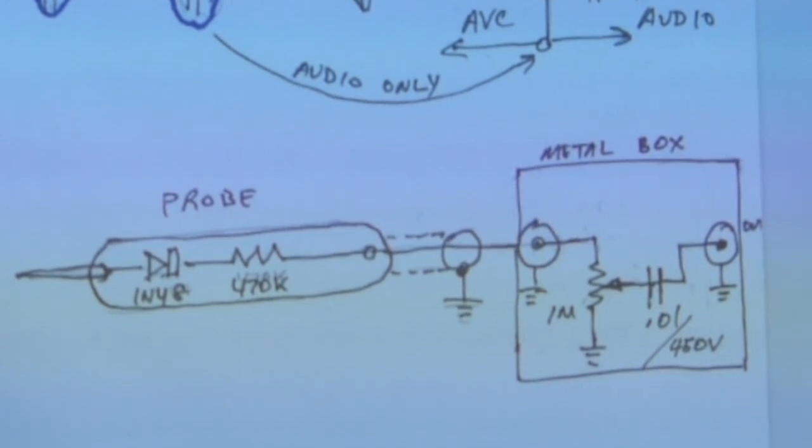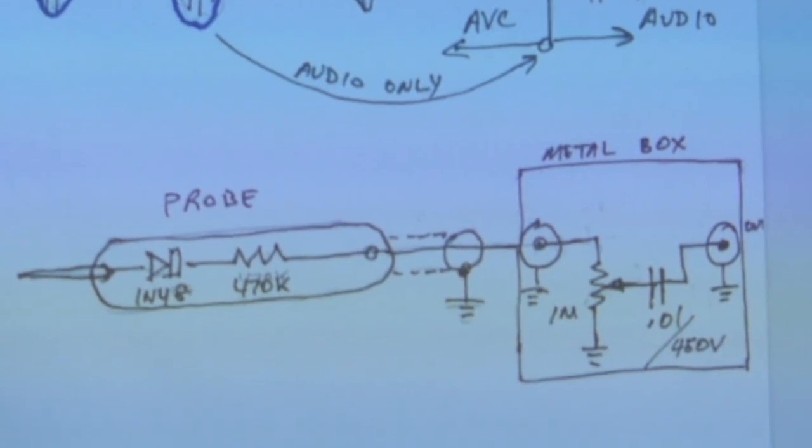So the 1N34 would work the same, I guess? Yeah, you could. I've never seen a 48. 48, yeah, okay. You just have to watch out for the PIV, the peak inverse voltage on a 1N34. But some of them are good for up to 60 volts, I believe, going from memory.